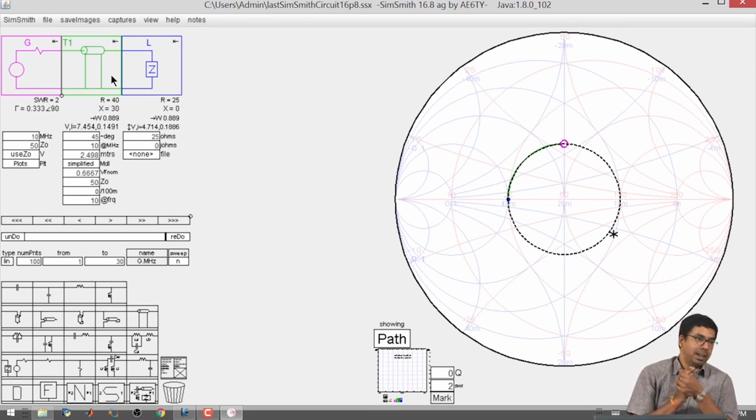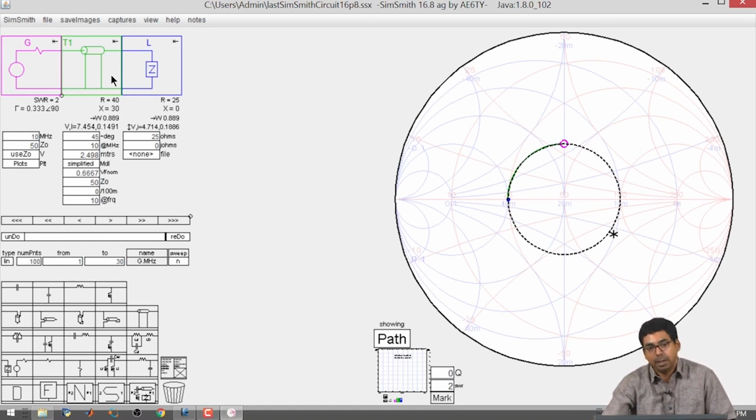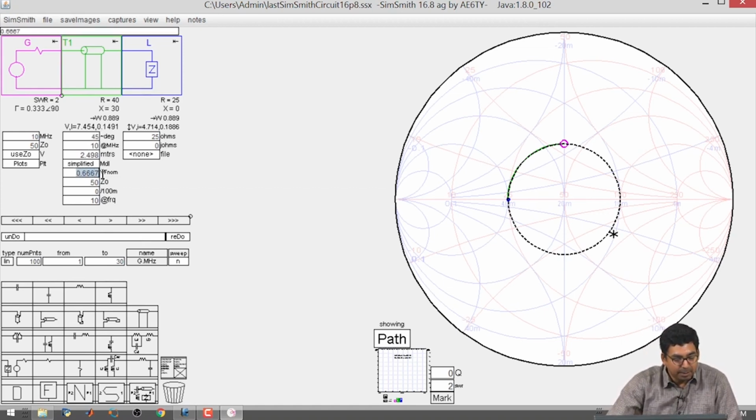Transmission lines are widely available for 50 ohms or 75 ohms. In this case, we are choosing a 50 ohm transmission line cable. It is a 50 ohms standard cable. The load is what we are trying to match. Okay. The load can be something else. Okay. So, here there are a few things that we are noticing. Okay. It says that 0.667 velocity factor.